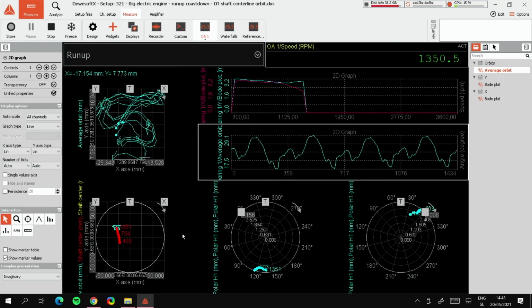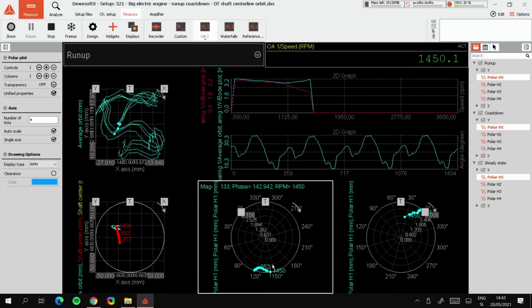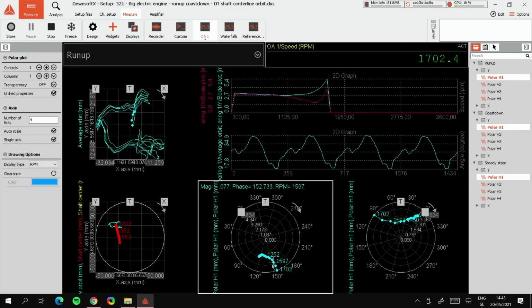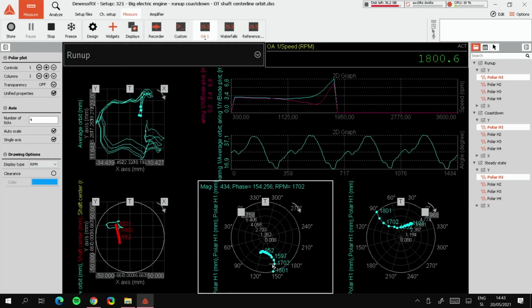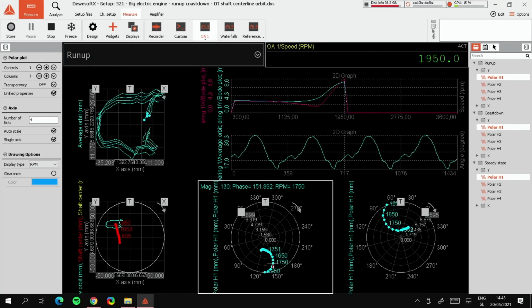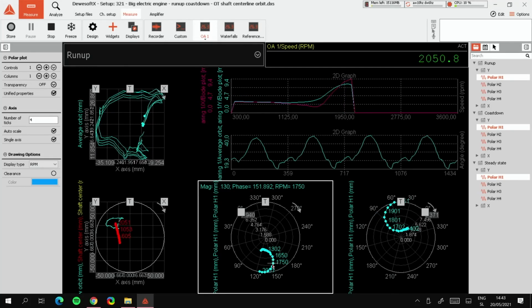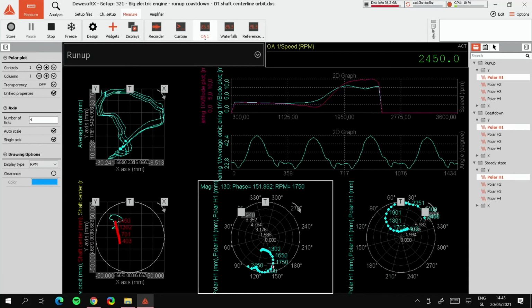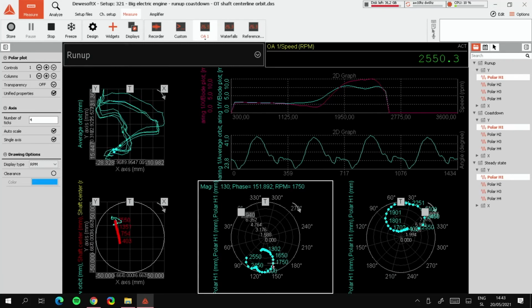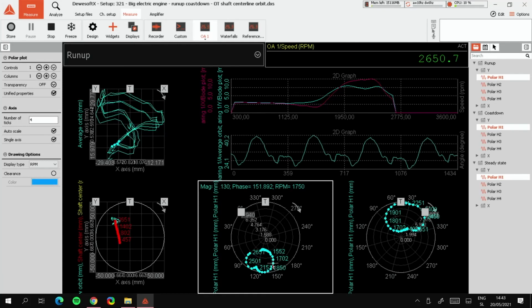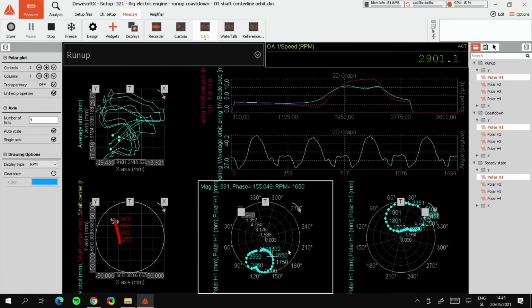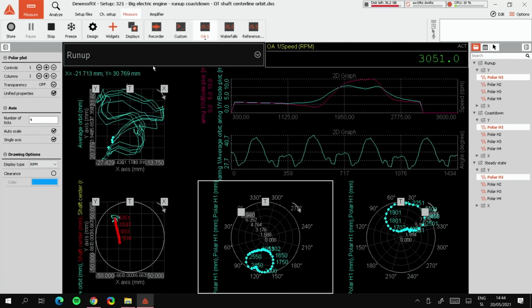All right, and then last but not least, the polar plot. The polar plot is a very important type of widget for orbit analysis because it contains a lot of data in a single display. Actually, it contains amplitude, phase, center line position, and RPM in the same graph. Again, same as with the shaft center line, because it has the center line data in here.